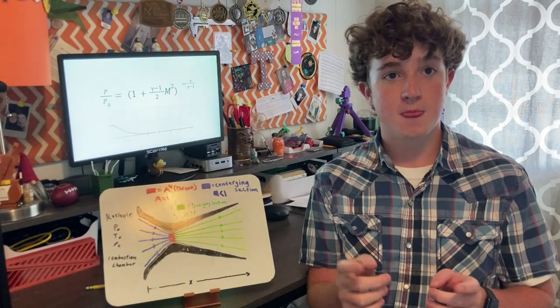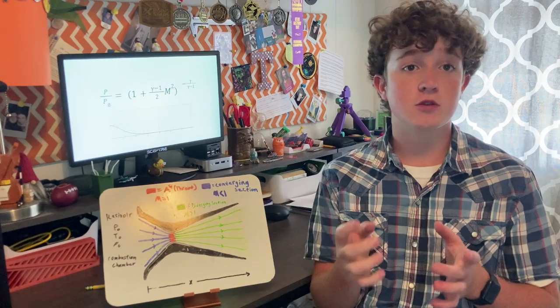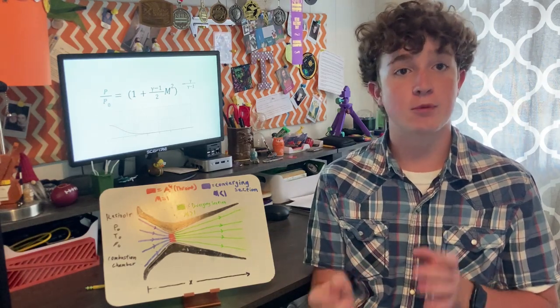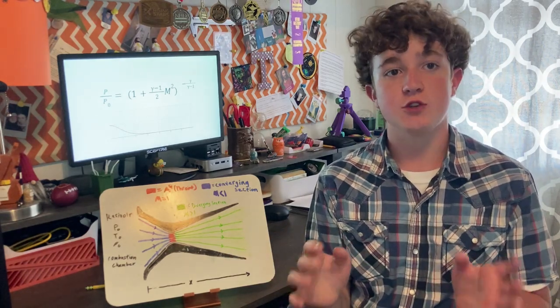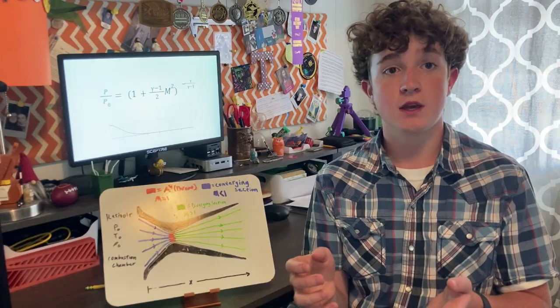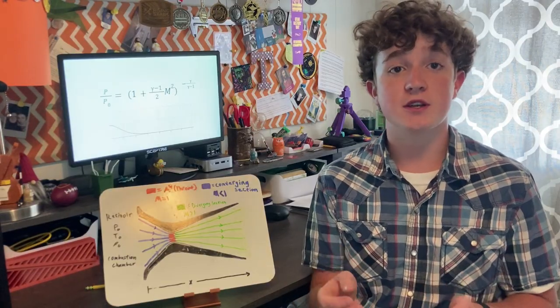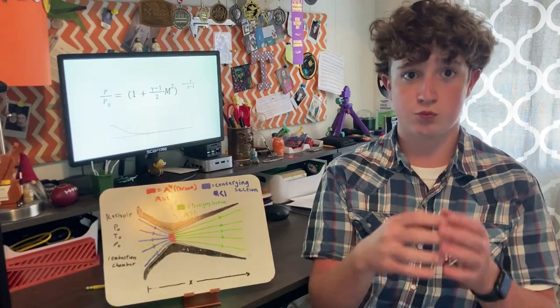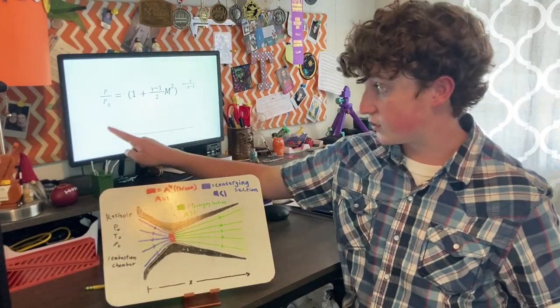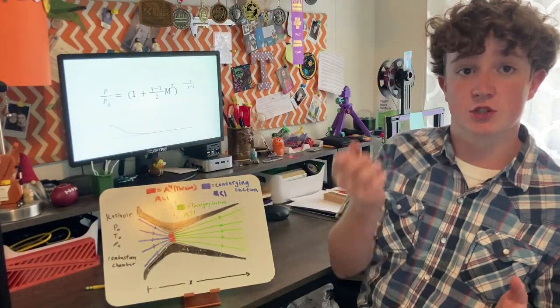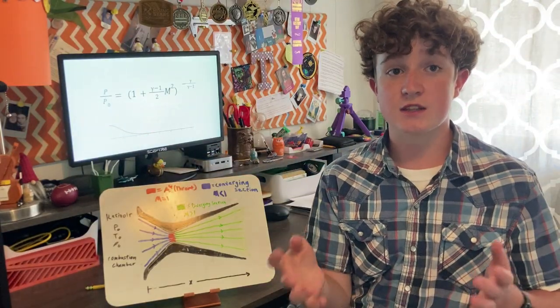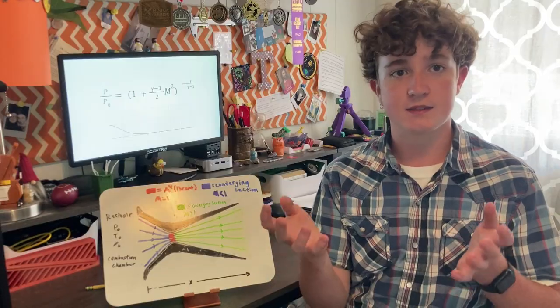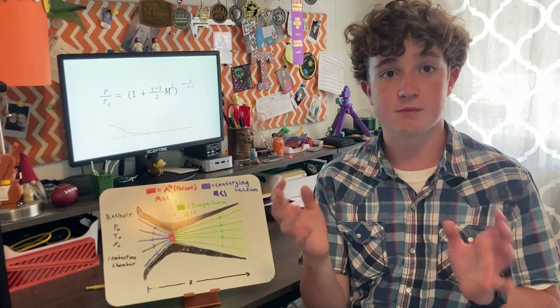Next is pressure. This equation is used to relate pressure along the nozzle to the chamber pressure. The same constants are used as in the equation for temperature. As we can see, as the Mach number continues to increase and we continue along the nozzle, the pressure decreases greatly. It is very steep, as we can see in this graph, compared to the temperature one. This then expands correctly to ambient pressure, that is generally most efficient and is correctly expanded.